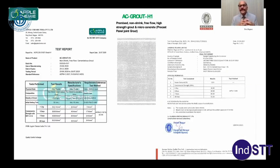But my main interest and concern is how you use the installation grout. See, there will be manufacturers. This is one of the best manufacturers. They have said that it will be a pre-mix, non-shrink, free flow, high strength panel grout or joint grout, and there will be a manufacturer test certificate. What is our duty as a consultant or a construction engineer? That you get it tested through a NABL accredited laboratory, verify the test parameters, verify the